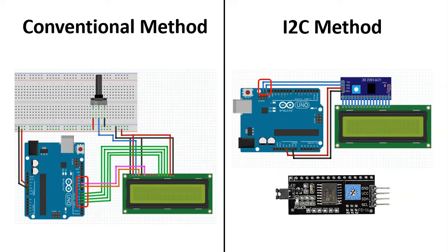And here we're sending data pins D7, 6, 5, and 4 from the LCD, which is taken 4 through 7 on the Arduino. And then we have a few others for enable, as you can see on pink, and then the RS go into 9 and 10. So you can see that it's taken a lot of the digital input outputs, whereas the I2C method, I mean,